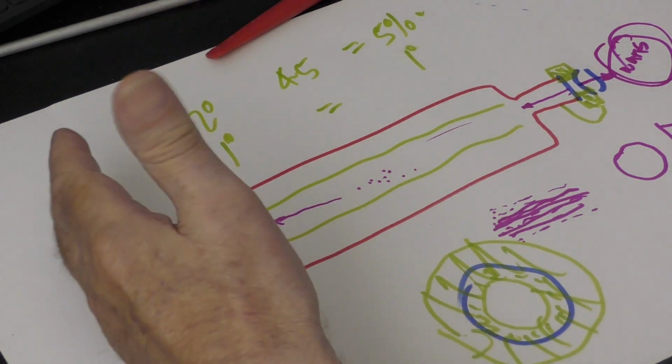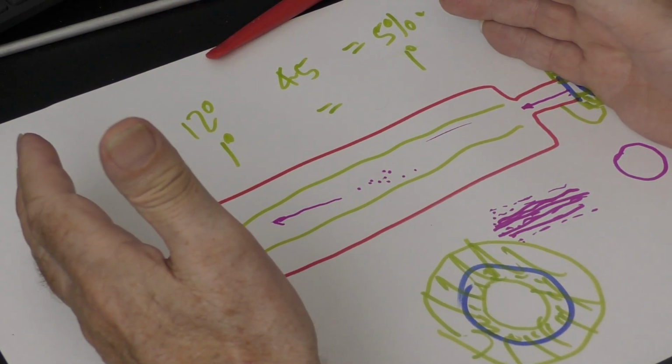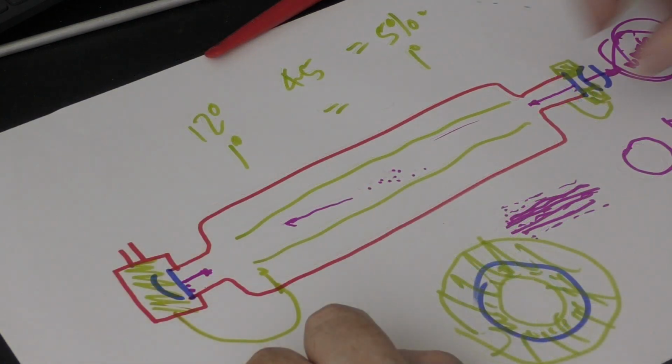And this explains why banding can occur. With an RF tube, I've explained to you how the dot size changes with exposure time. That's not the same as with a glass tube. With a glass tube, the pixels always remain basically the same size. And what you get is a different amount of colour, if you like, in the pixel because the power changes.